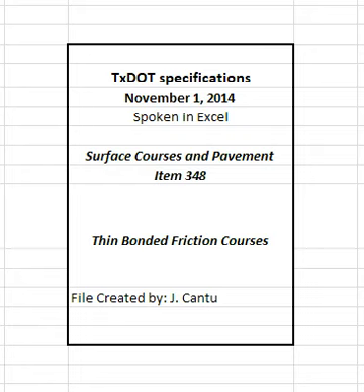4.9.4 Operational Tolerances. Control the production process within the operational tolerances listed in Table 9. Suspend production and placement operations when production or placement test results exceed the tolerances listed in Table 9 unless otherwise allowed. The engineer will allow suspended production to resume when test results or other information indicates the next mixture produced will be within the operational tolerances.